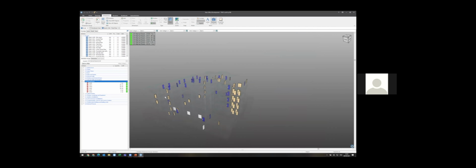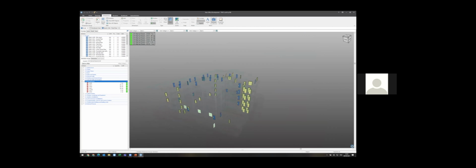So we can see that on the left-hand side here. If I look into, say, 2.8 internal doors, I can right-click, I can isolate that folder, and if I zoom out, we can then see the grouping of those doors into their individual dimension groups, which correlate with my rate library. So 2.8.B, if I click on that now, it's highlighted these doors in green, so they're sort of double door sets are 2.8.B. 2.8.C are just these single doors, and then by clicking through the rest, we can kind of see the rest of them highlighting.